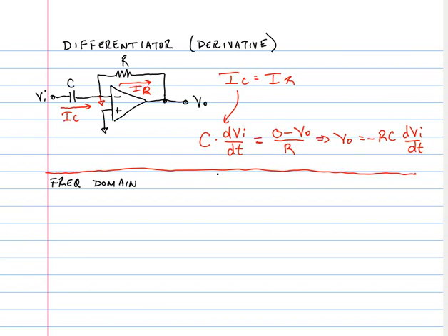We can see, remember, the impedance for a capacitor is equal to 1 divided by i times 2 times pi times the frequency times C. I'm going to make a substitution and call i times 2 pi f a variable that we'll call S. This variable S is proportional to frequency. So we can rewrite this as 1 divided by S times C. Recall, impedance of a resistor is simply the resistance.